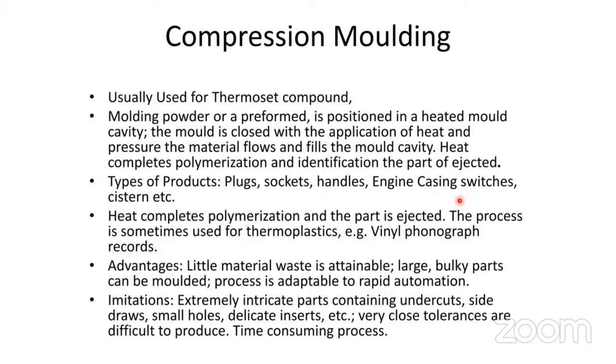Now, what are the advantages of this process? Little material waste is attainable because we are using the preform or tablet. Large articles you can manufacture, bulky parts can be molded, and the process is adaptable to rapid automation.